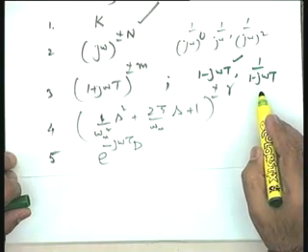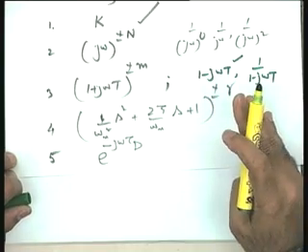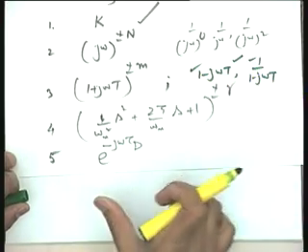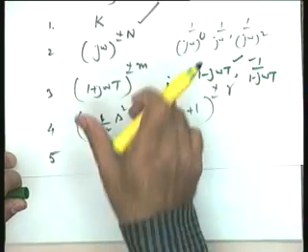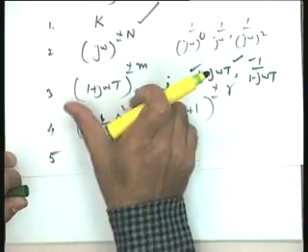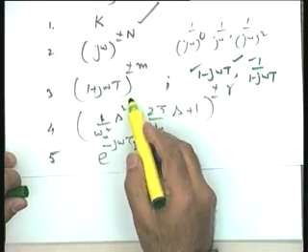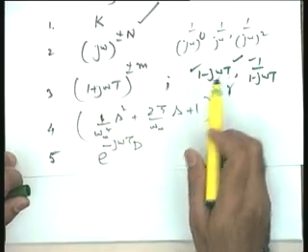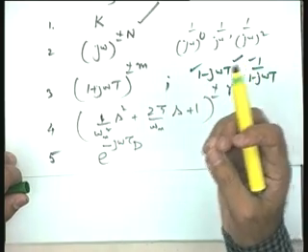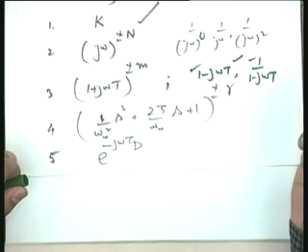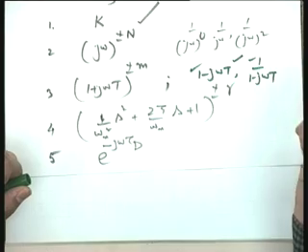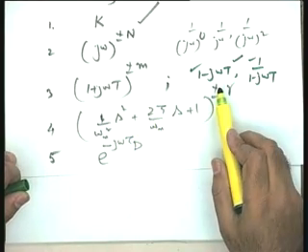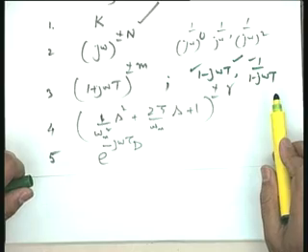This possibility simply means that the pole of the system is in the right half plane. I am not listing them as a separate building block because it is so easy to convert the construction of this building block into this form, because the magnitude will remain the same, the phase angle will simply get reversed. The minus sign will come. That is the only change that will come if instead of 1 plus j omega T, I have the factor 1 minus j omega T.